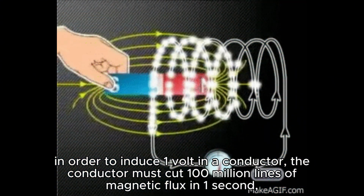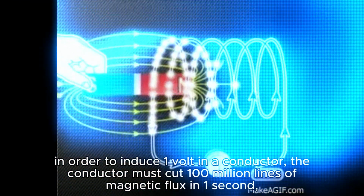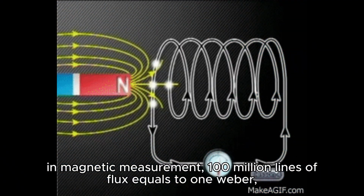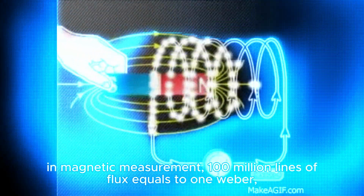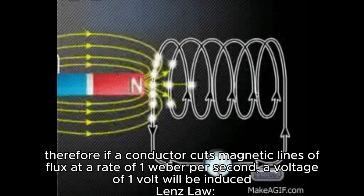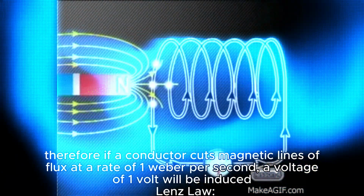In order to induce 1 volt in a conductor, the conductor must cut 100 million lines of magnetic flux in 1 second. In magnetic measurement, 100 million lines of flux equals 1 Weber. Therefore, if a conductor cuts magnetic lines of flux at a rate of 1 Weber per second, a voltage of 1 volt will be induced.